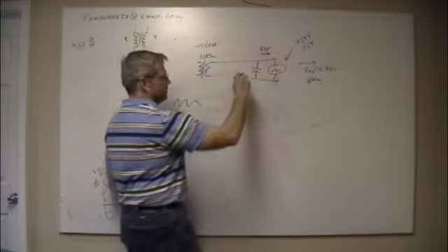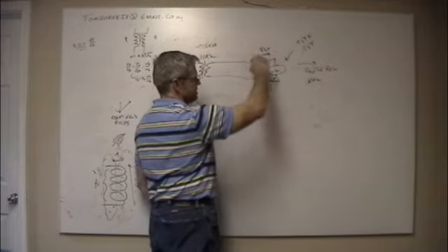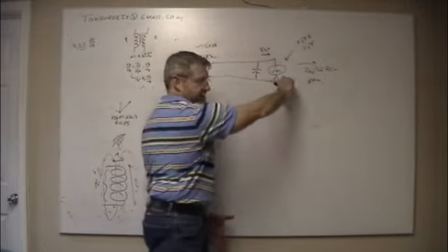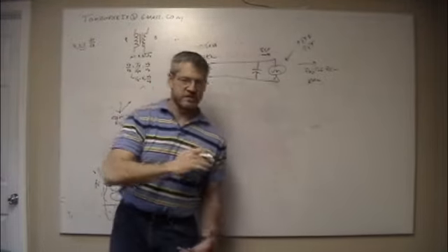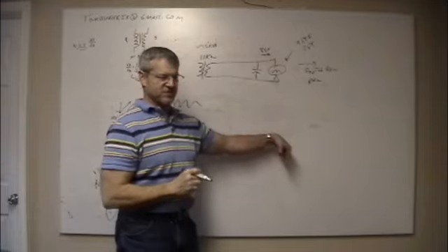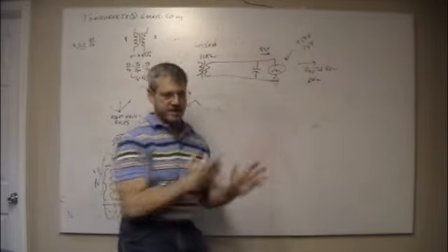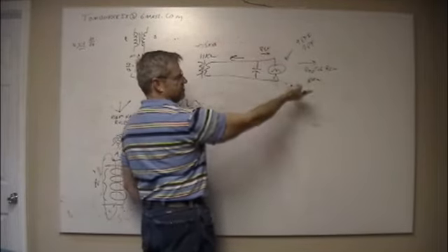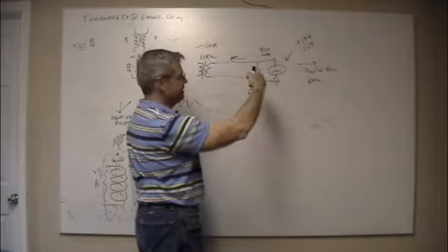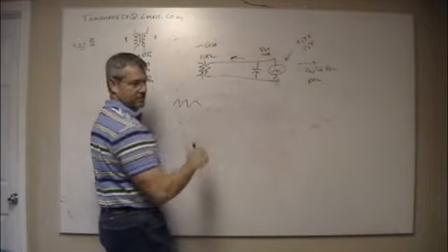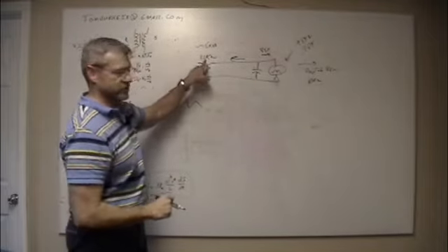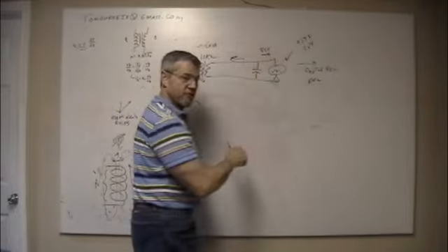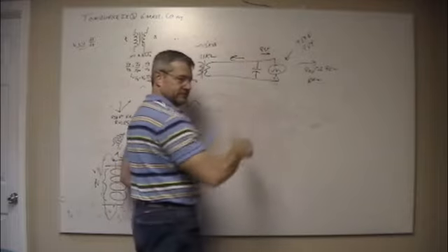And now, when he's charging up at his peak, he looks like a short, and he gives me his energy ahead of when he needs it. So he absorbs all this energy, and now he's trying to use it when it's stupid to use it because the voltage has gone lower, but now he can supply the current. And then what I see back here is a power factor that moves back up to 0.95, and now I can go back closer to an 11 kVA transformer because I've done what's called power factor correction right here.